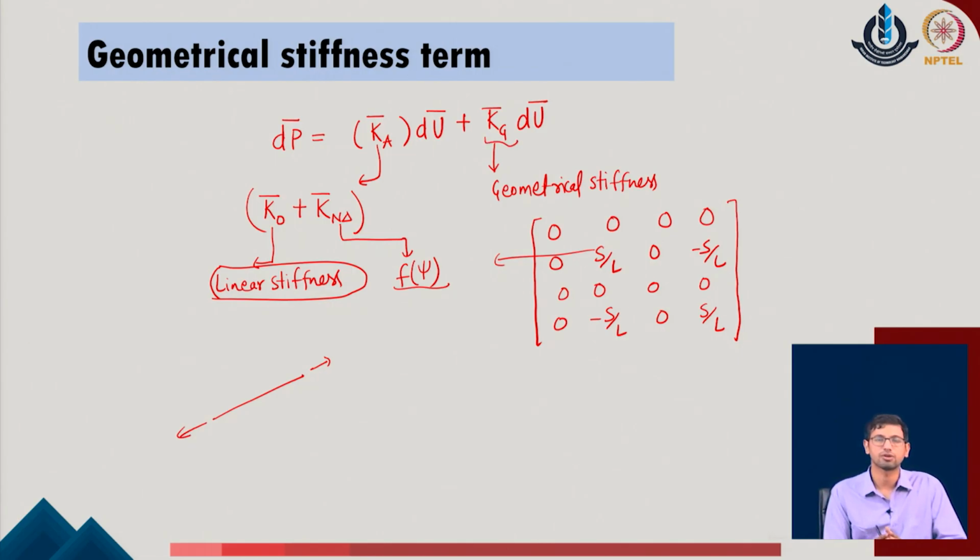This brings a very important point in the whole discussion: the stiffness of the system is not only getting modified due to the large displacements which are taking place in the system, but also due to the forces which are active in the given system, and once these large deformations are active, these forces are also modifying the stiffness of the given system.